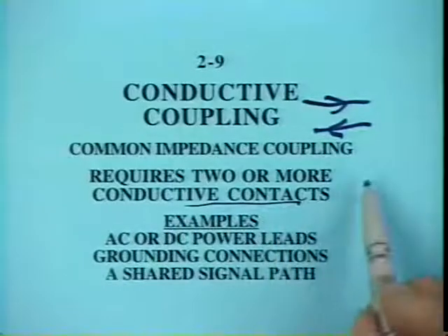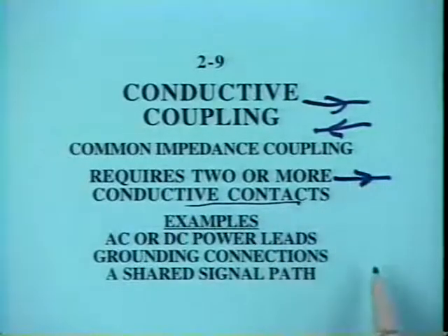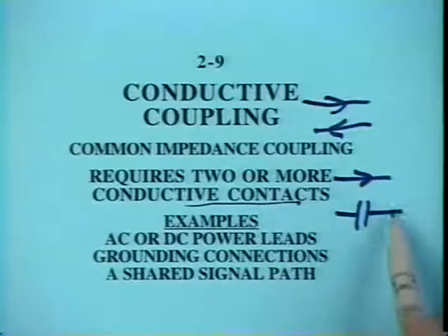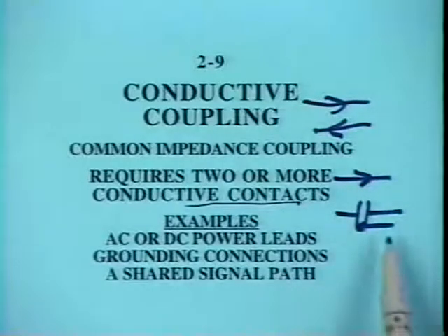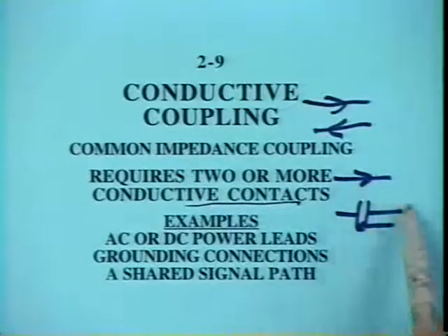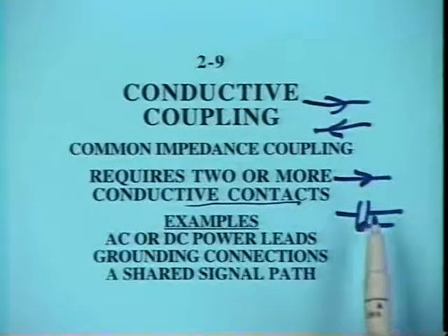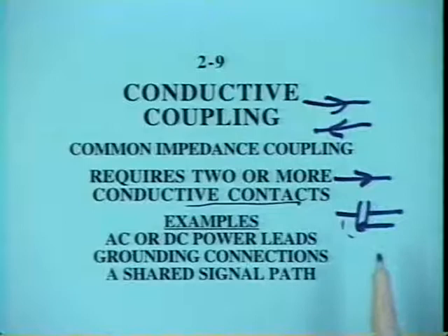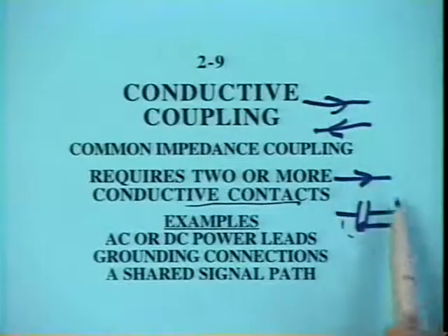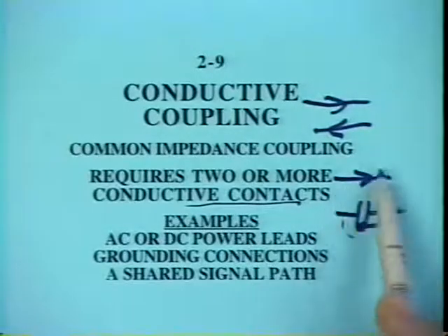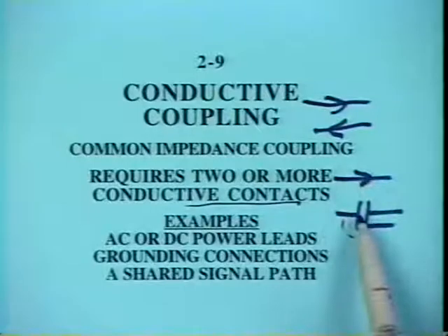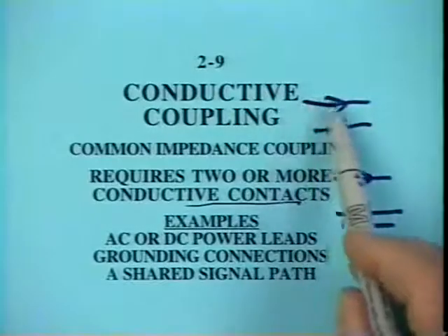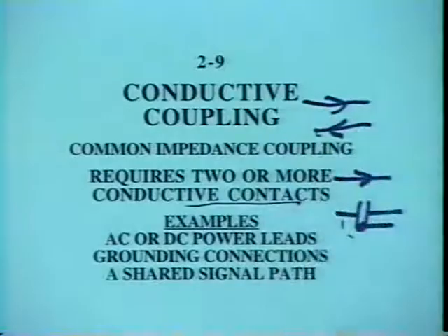Now, you could say, well, what if we have one conductive path out, but instead of a second conductive path back, what if we have a capacitive connection that returns the current back to its source? Yes, we have that very often, but we're going to call that electric field coupling. This unintentional capacitance between the two circuits will be the dominating factor here. And so this will be described as a mutual capacitance, that is an electric field coupling problem, whereas this is purely a conductively coupled problem.